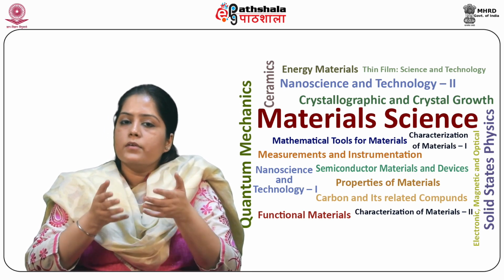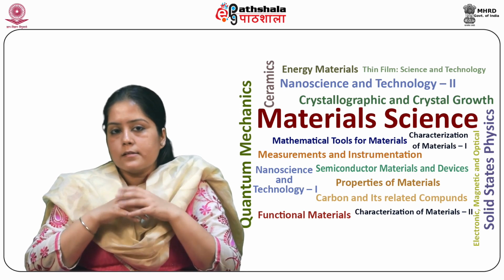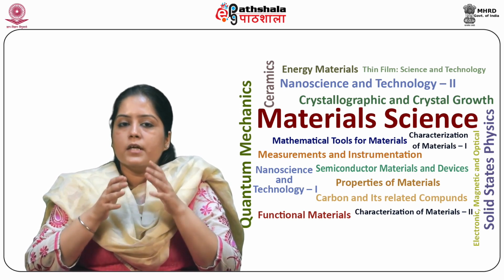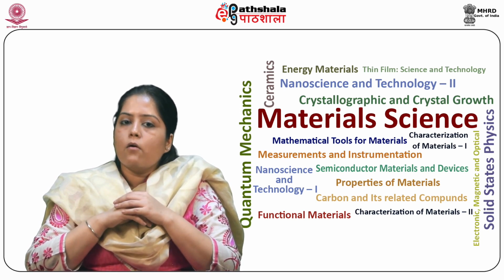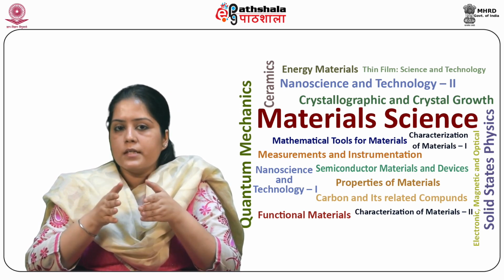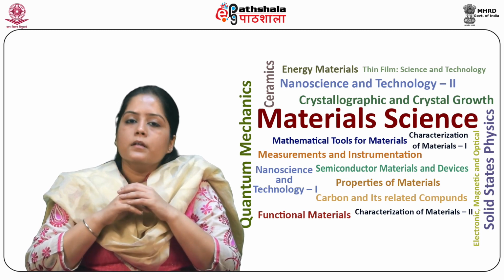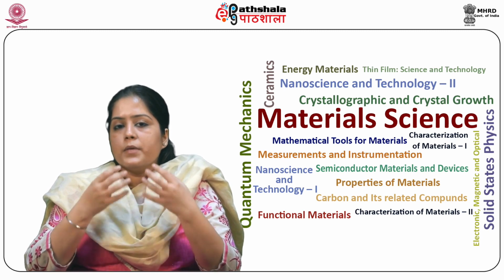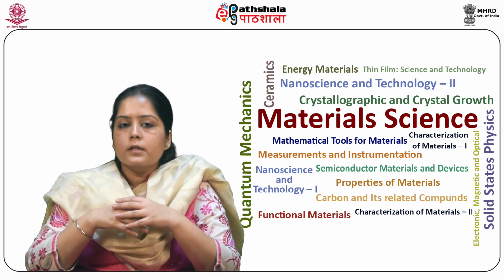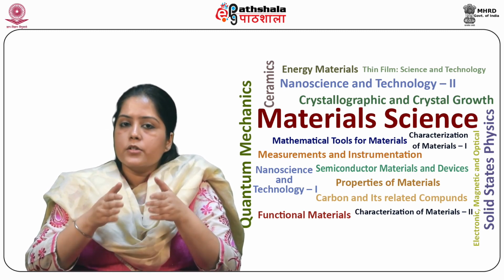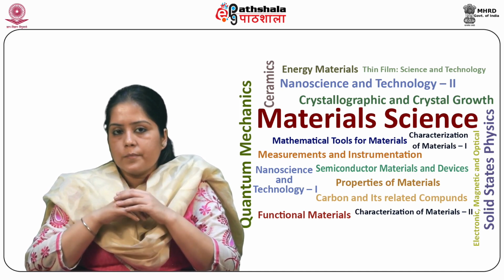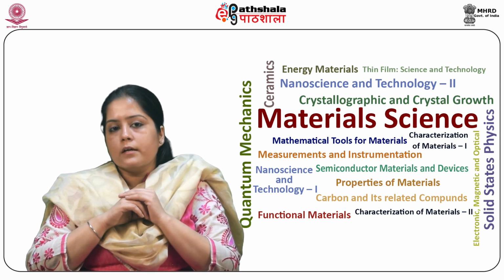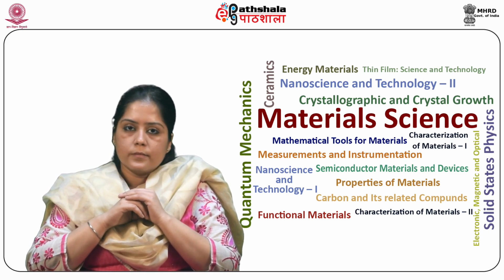It should be abundant, cheap and eco-friendly material. There can be convenience of shapes and sizes. It should have simple and inexpensive integrated processing or manufacturability, and it should have the minimum material and the minimum energy input. The energy payback period should be less than 2 years. It should be highly stable and long life, greater than 20 years.